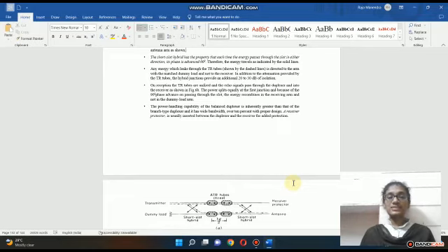The power splits equally at the first junction, and because of the 90 degree advance on passing through the slot, the energy recombines in the receiving arm and not in the dummy load arm. The power handling capability of the balanced duplexer is inherently greater than that of the branch type duplexer, and it has wide bandwidth, over 10% with proper design. A receiver protector is usually inserted between the duplexer and receiver for added protection.